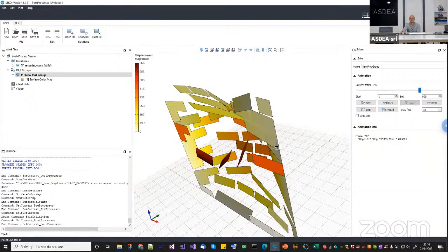Is a hysteretic material required? Yes, it's a hysteretic material, and I prefer it when doing dynamic analysis. I prefer the hysteretic material because, first of all, you can modulate how large the envelope should be, how the hysteretic loop should look, through the pinching parameters. And second, because it can include stiffness degradation.